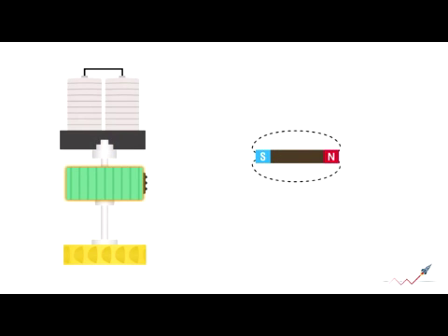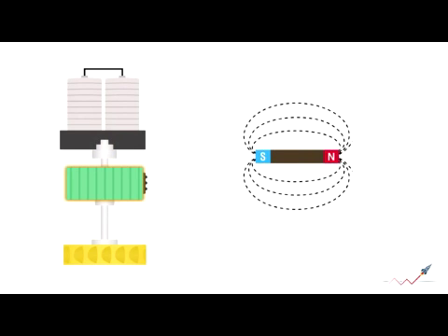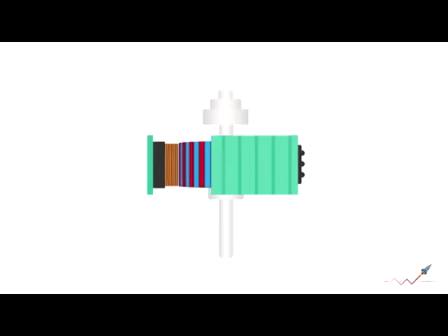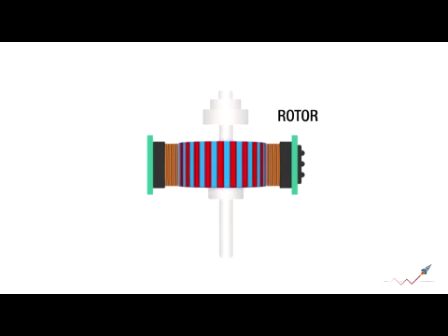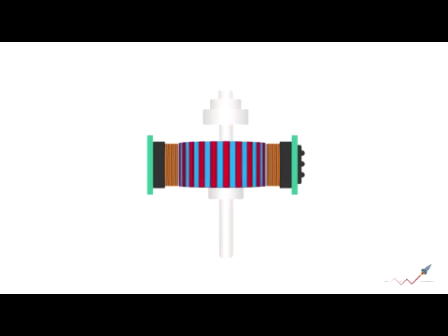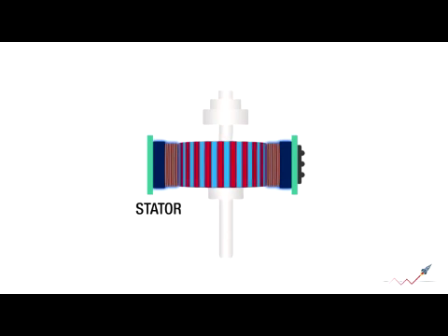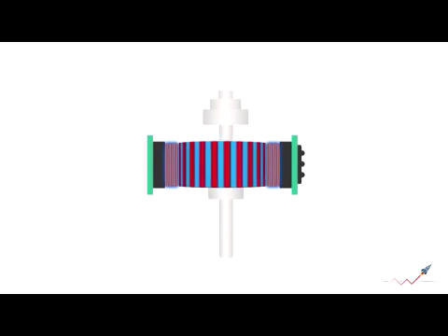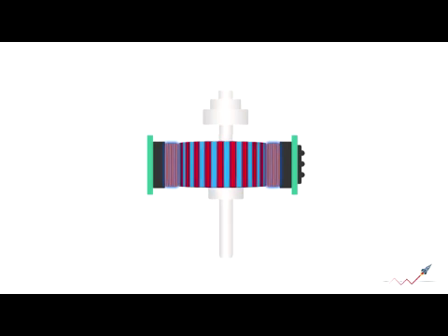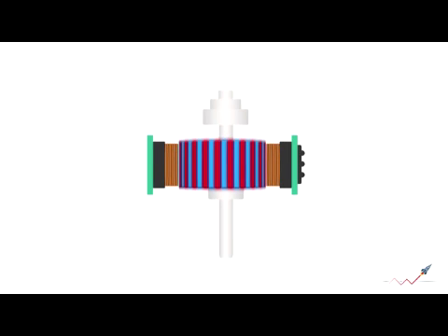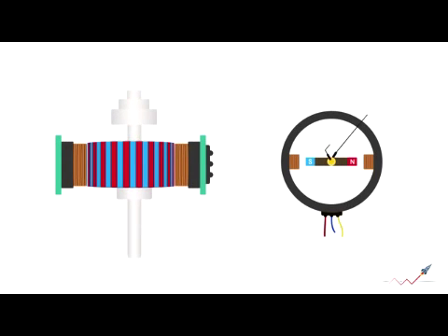The working of an AC generator depends on electromagnetic induction. Inside the generator is a rotor, which is driven by the spindle. Outside the rotor, the stationary part is a stator, which is made up of 3 coils of copper wires called winding. On a rotor, there are a number of electromagnets powered by the DC current through the exciter. The magnets are lined up in a way that adjacent poles have opposite fields to each other.